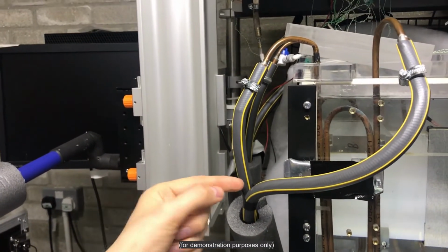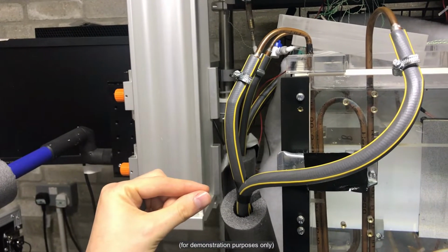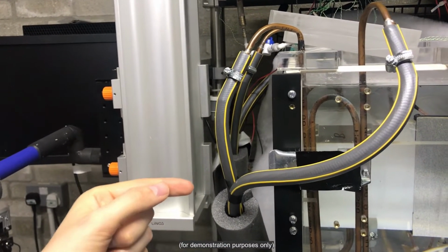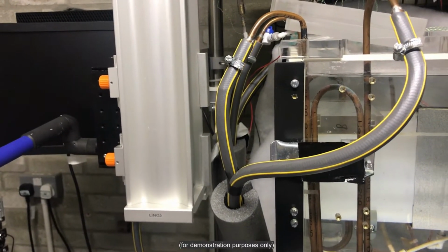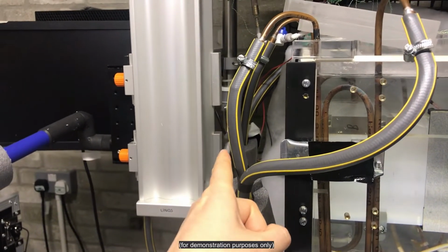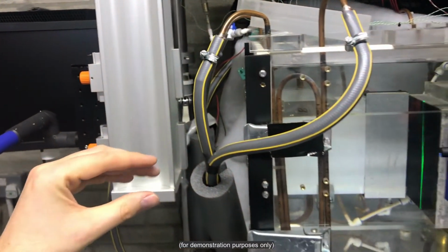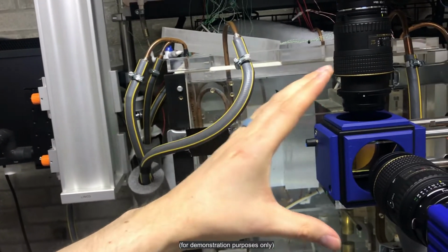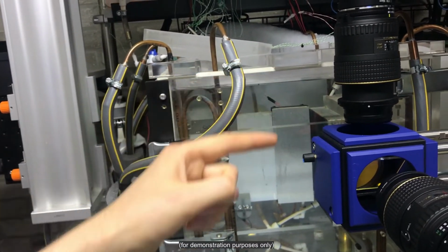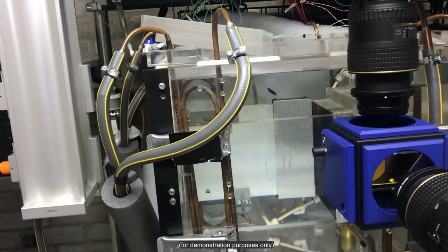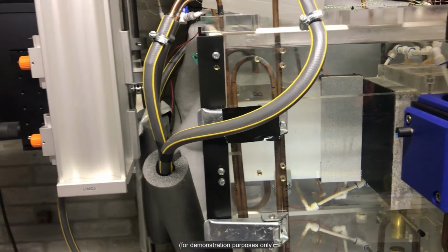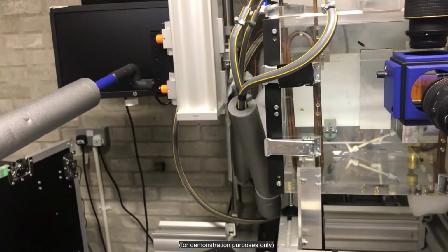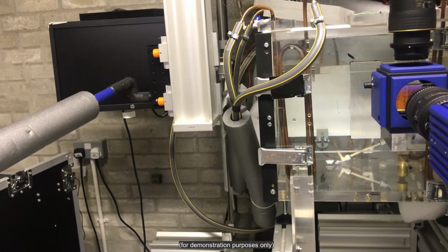Another general rule of thumb is this is where the laser beam is coming out, and right as it comes out of the lens, it's effectively still a beam, and at that point it is most dangerous. So try and avoid looking where the beam is. As it starts to diverge and spread out, the intensity of the light is not so strong. However, it is still sufficient at full power to provide a genuine risk, and of course you should never take off your goggles.